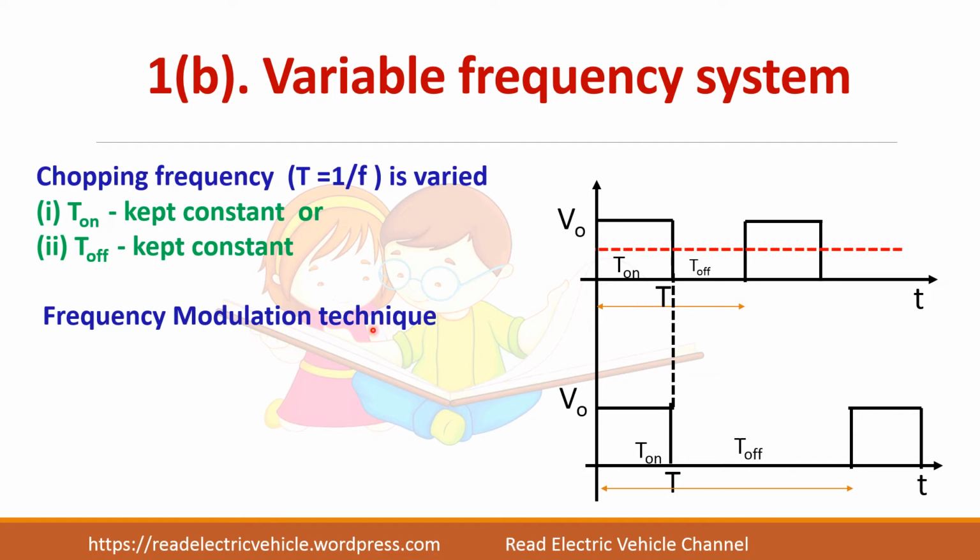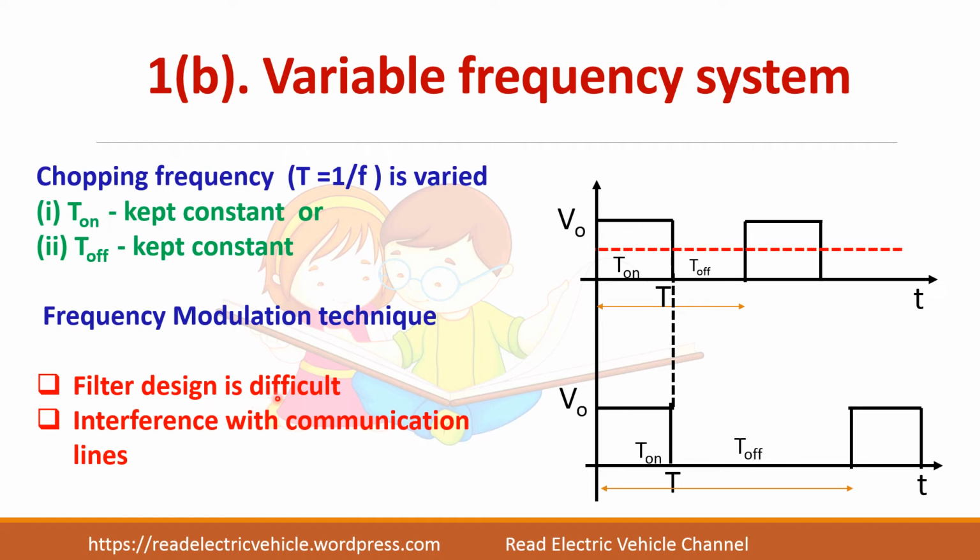So it is called frequency modulation technique, but this method has some disadvantages, like filter design is difficult because frequency keeps on changing. And another problem is it may interfere with the communication lines because frequency is involved, so it may cause interference.